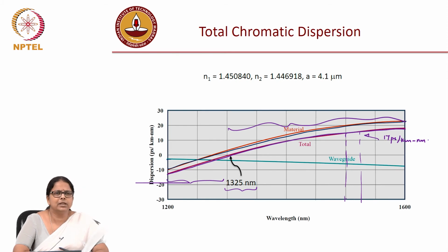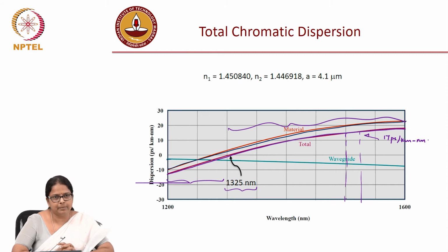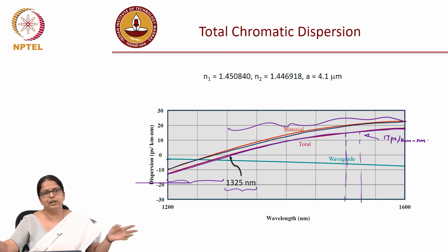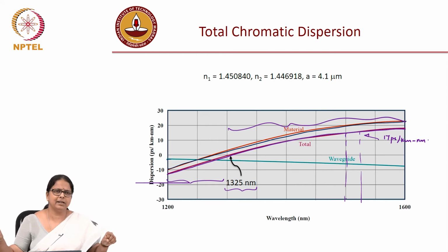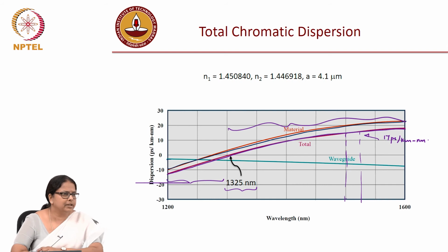Of course, you could have used a semiconductor optical amplifier, but that is more noisy and so on. Raman amplifier is another amplifier that is used, but only for some specialized systems. The reason being, the pump power that you need to put into the system to initiate the Raman process is really high. So, it is not used in regular networks. You have some specialized undersea networks where there is no operator going and digging every day, right? For those kinds of networks you use Raman amplifiers, but not for regular commercial communication systems, let us say terrestrial communication systems.